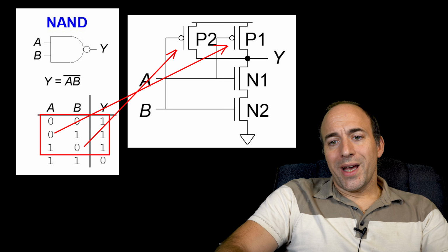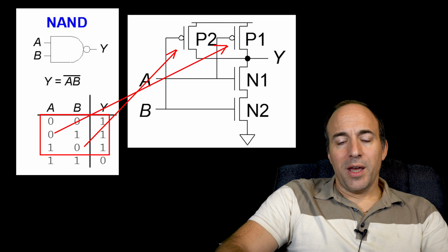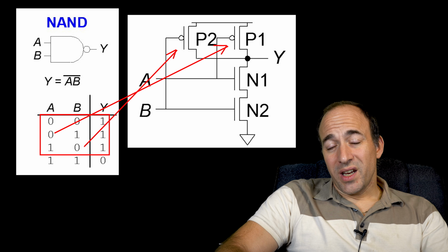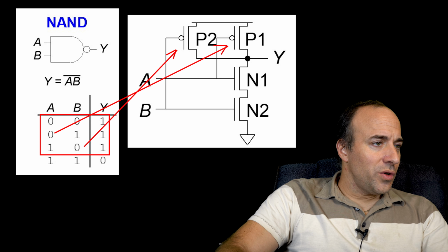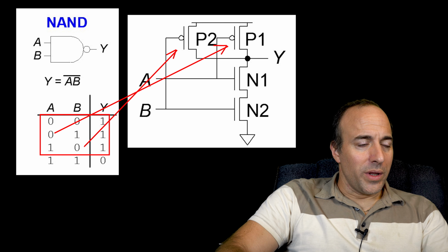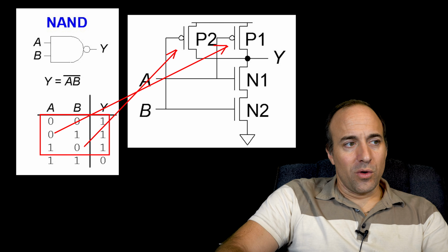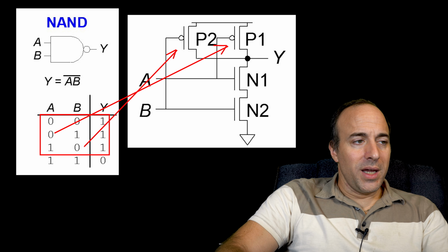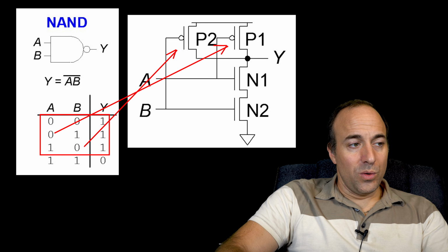The first row has a 0 input value for A and B. This means that you would have a PFET for each of these inputs connected in series. If we go to the next row with a 1 output, A is 0, B is 1, so we ignore B. So for A, we have a PFET connected from the output to VDD.